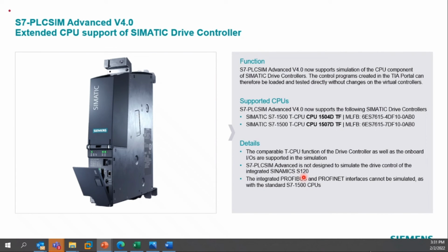Another feature is for Simatic Drive Controller, where you have support for simulating the T CPUs, like CPU 1507D TF or 1504D TF CPUs. With the onboard IO controls, it can be simulated, but you cannot simulate the integrated S120 part, only the T CPU part can be simulated.